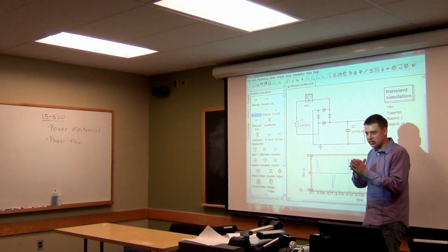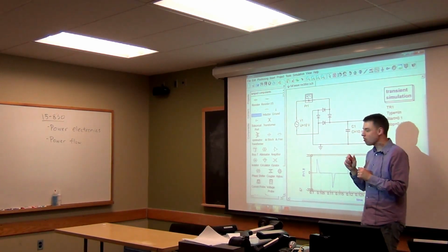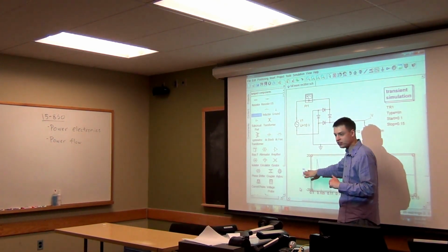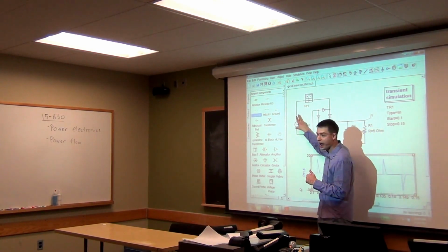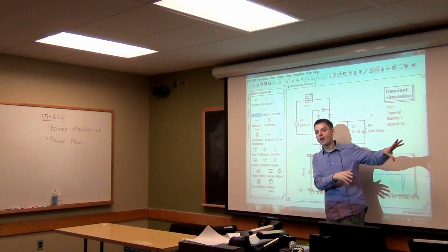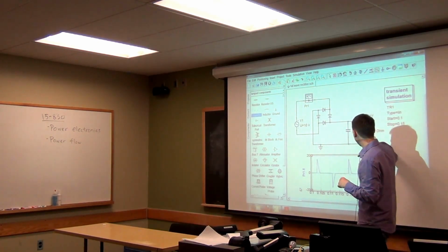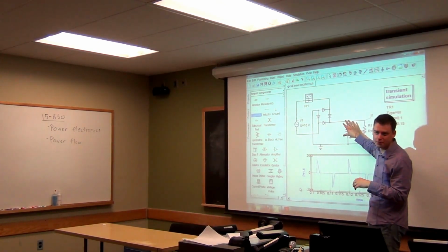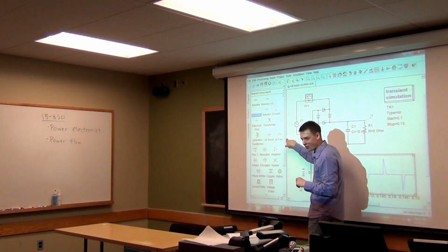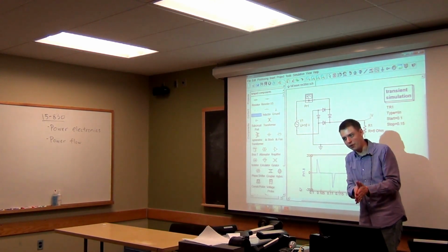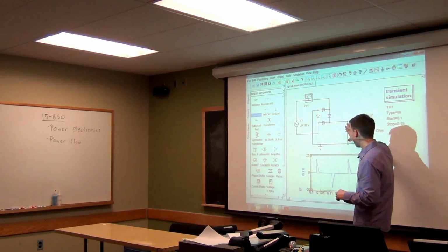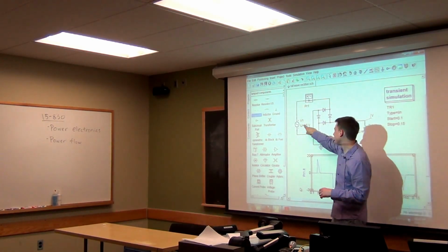At a certain point, though, this switches. And all of a sudden, in the waveform here, remember, the steady state it settled to was like 7 or 8 DC. So this will go higher than that. And when it goes higher, all of a sudden, it'll want to start drawing current, both to go through the load itself and to fill up the capacitor. So you'll start drawing current. Then you start kind of tapering this off. The capacitor starts filling up a little bit more. And so that causes this to taper off more gently, up until the point where the capacitor, again, is higher charged than this voltage up here.